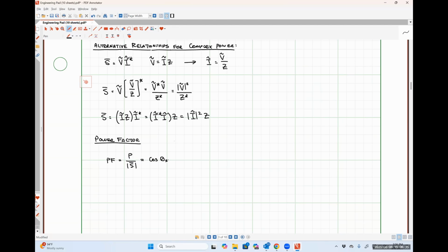When we pay our electrical utility bill, essentially what we are paying for is the average power that we consume over the duration of the billing cycle, right? So if you took your energy usage in kilowatt hours for a month and you divided it by the total number of hours in that month, you would literally have the average power that you consume, okay?